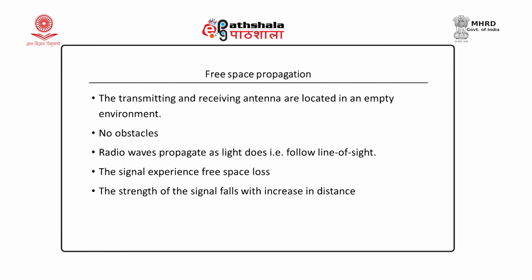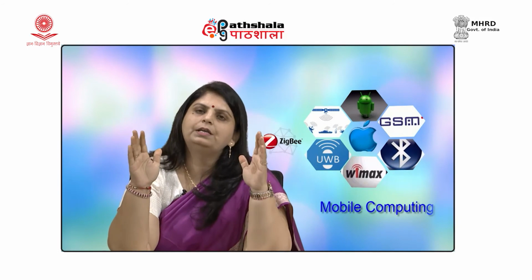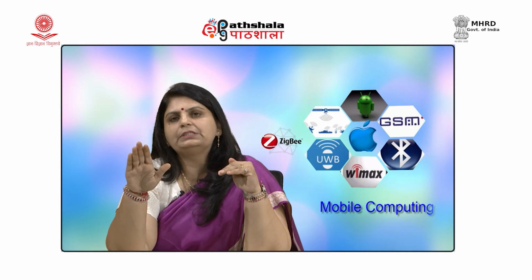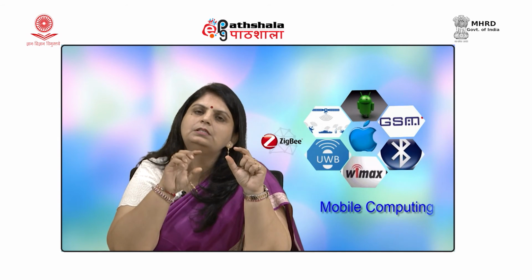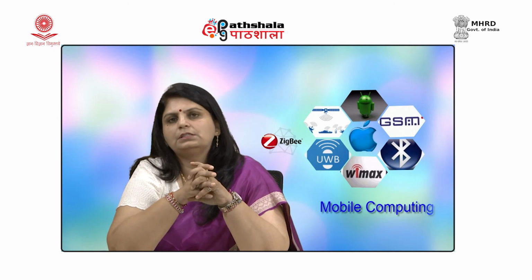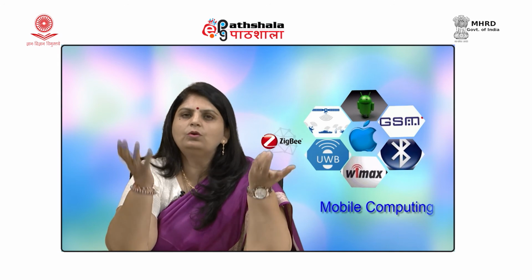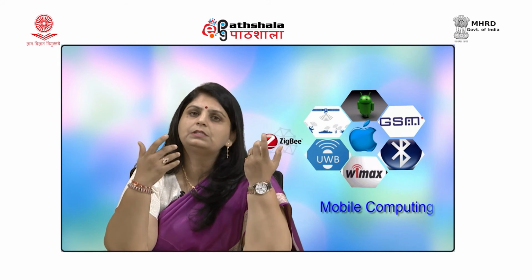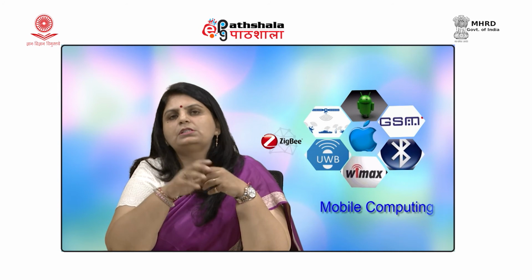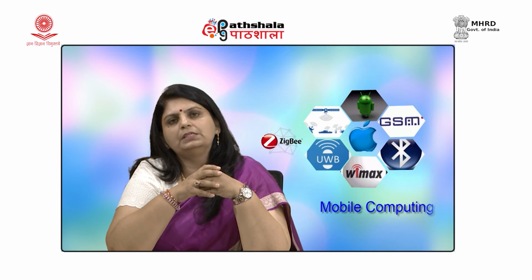Free space propagation is when the transmitter and receiver are in line of sight with each other. There are no objects in between. The signal simply goes from the transmitter and reaches the receiver. So, what should happen? That there should be no signal loss also. There are no objects, it is vacuum, it is free space, but still there is a reduction in the strength of the signal, which is known as free space loss.